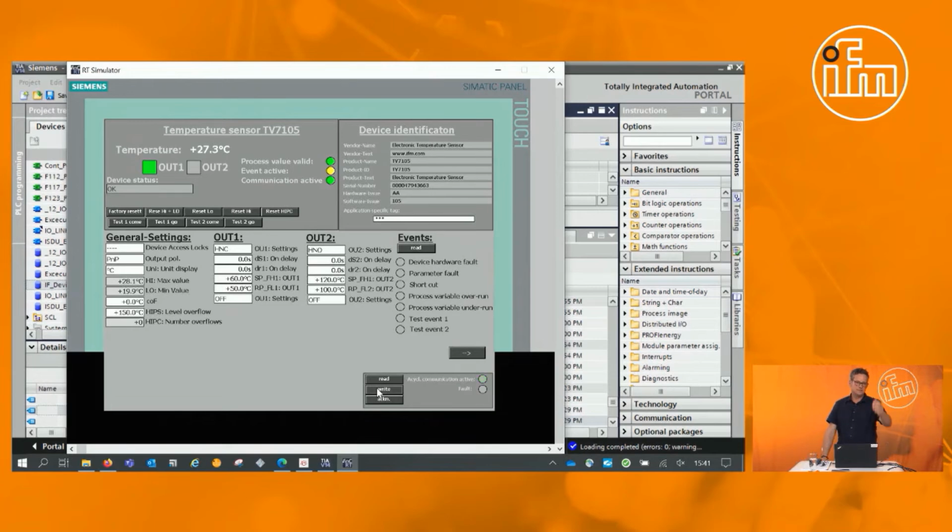And you see the field is green now, which means I have changed inside the device the behavior of the switching point 1 and downloaded that over my PLC, over my function block in the device, and now it's working as I want to have it without pressing push buttons or taking the software Moneo Configure or any other software. I've just done everything inside my PLC.